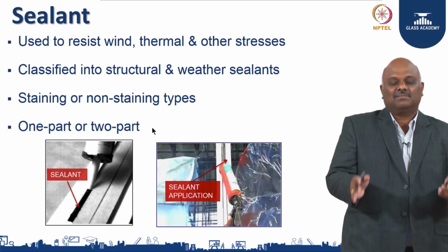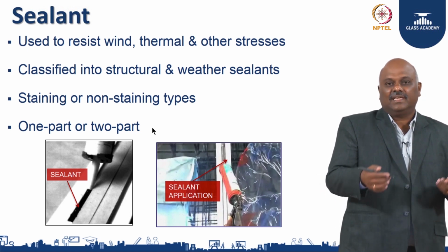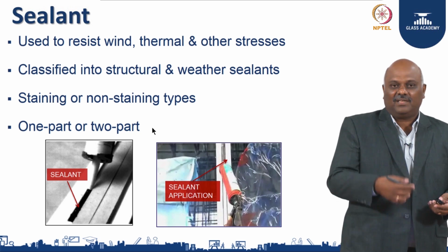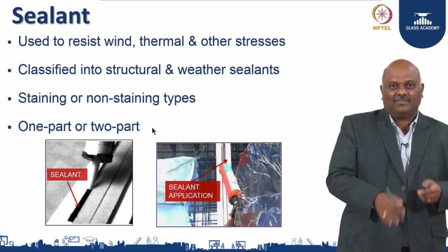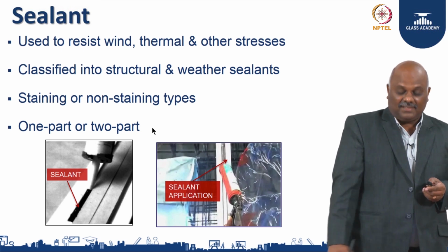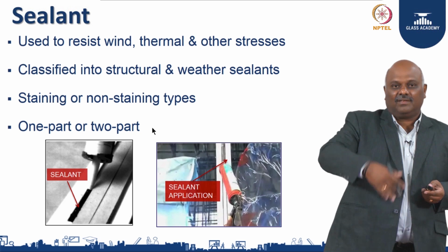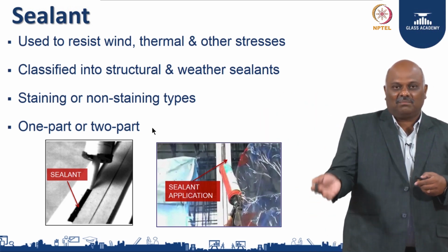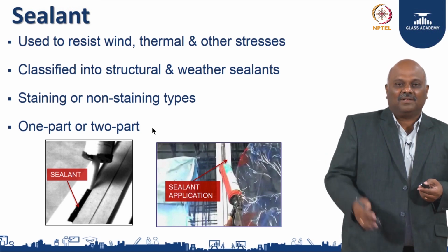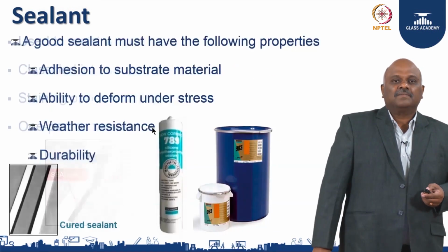So, here I am just simply telling you how it goes with the fundamentals of facade, that is all, not going in depth on what sealant is made of and how it works, because that will be taken care of by our colleagues in depth for you. So, it is much easier. Commonly these are the two sealants you use, and inside that you have various sealants available, 2 part and 1 part, non-bleeding, non-staining, a lot of things are available, but commonly structural and weather sealant.